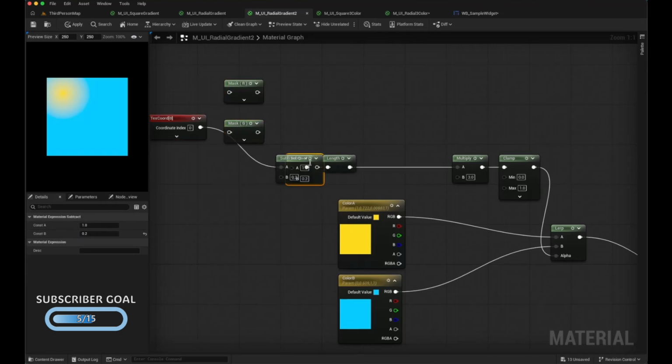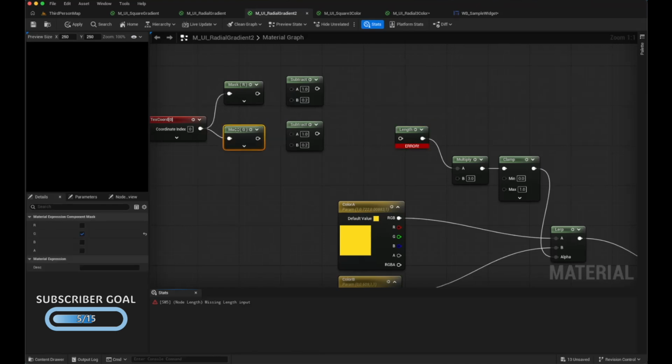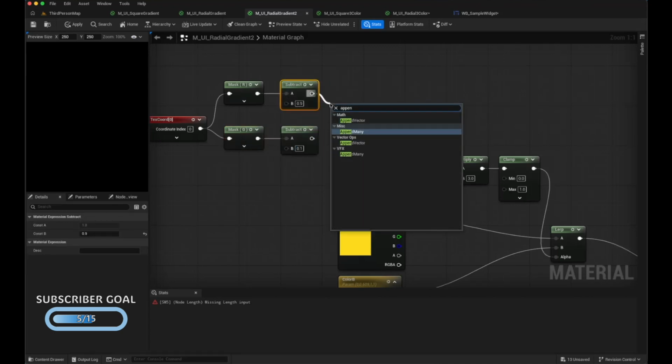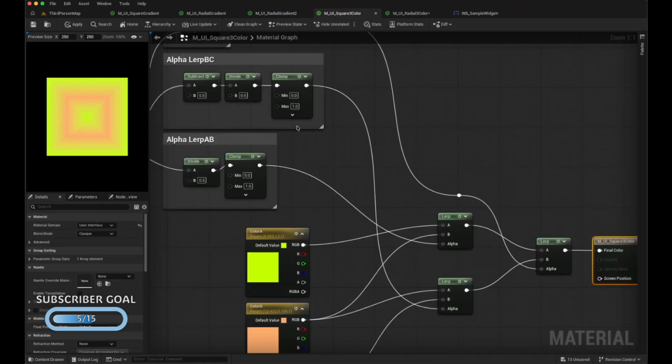We will also duplicate the subtract node. So one subtract goes on the top and one subtract goes on the bottom. We will connect our pins, R and G. Now remember, this was 0.9 and this one was 0.1. Now we have to combine these values back together. For this purpose, we have the append node. Append vector. We'll connect our pins and attach this to the length. And there we go. We have the square gradient.